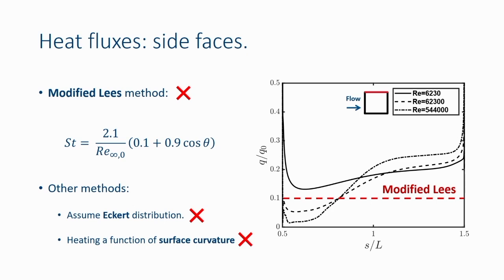And the reason for that is satellites fail, not because things burn away, not because of ablation, but because they're glued together. The joints fail at the corners, right? The epoxy joints which hold the satellite together fail. And therefore, it's really important that we get this region correct, because that will give us the best indication of when this satellite might fall apart and fragment.